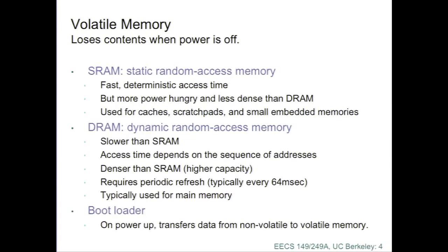So those are all non-volatile in the sense that you remove power, the data stays there. Okay, volatile memories, if they lose power, they lose data, and in fact, dynamic RAMs can lose data even if they still have power. Dynamic RAMs are essentially capacitors controlled by a single transistor, and there's leakage, and they forget.